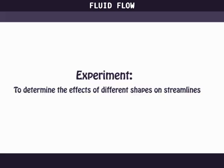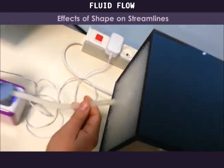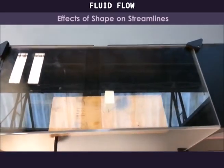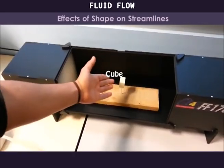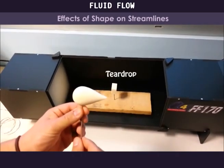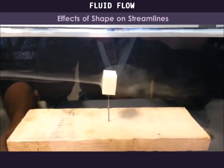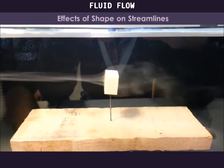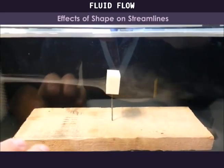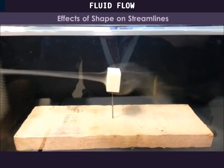Let us perform an experiment to determine how different shapes affect streamlines. We shall put different shapes on the path of a stream of smoke and see the flow in front and behind the different shapes. A cube, a hollow sphere, and a teardrop. For the cube, we can see streamlines before hitting the solid, but they are then broken into a disorderly flow behind the cube.